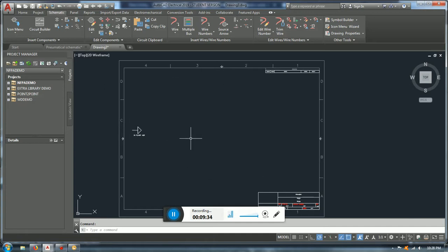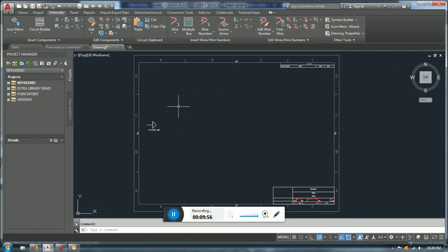If this is gonna get too big, or sorry, the template is gonna be too small, I could use a C size. I'm talking about ANSI in the US. If you want the equivalent in Europe, a C size is equivalent to an A2, and a D size is equivalent to an A1. You can always go to an A0, but that is very big.